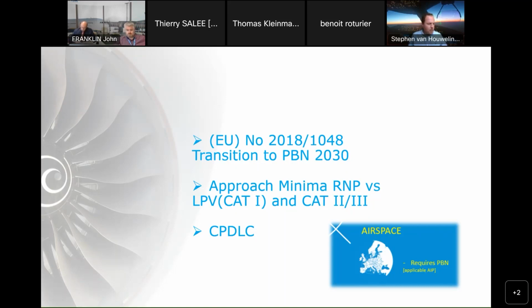I see the change. For example, if I fly from Amsterdam towards the southern part of Europe, in the beginning we log on, but I see there's a transition period, because there's a combination of voice and CPDLC messages. So the CPDLC says contact the next frequency and we accept, but then via voice we get the descent clearance or the climb clearance. So it's not fully integrated yet, so there's still some challenge, I think, to gain the benefit from CPDLC, because I really like it.